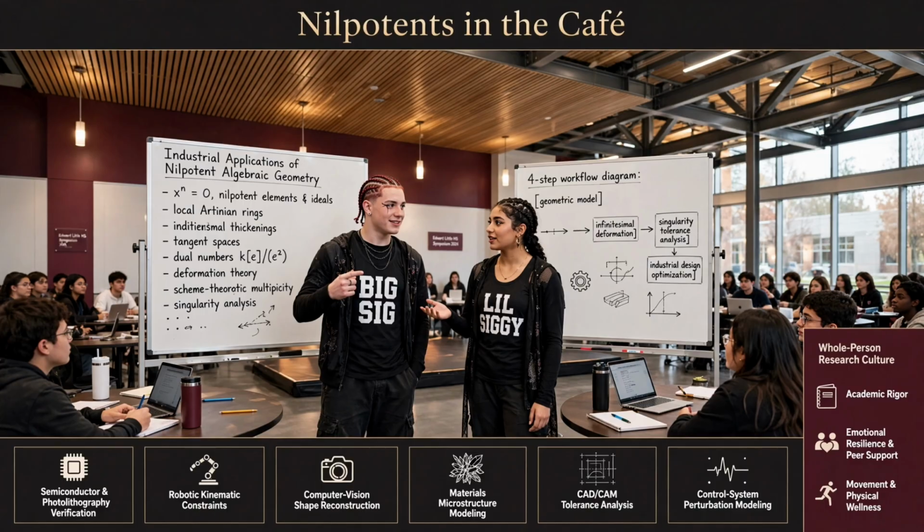Exactly. And this brings us right back to our algebraic geometry. We know we can't use the useless linear approximation, so what do we do? We construct a nilpotent approximation? Yes. We construct a nilpotent approximation of the control vector fields. We inject our self-destructing epsilon into the robot's navigation matrices. Wow. The complex nonlinear dynamics of the physical robot are replaced by a nilpotent Lie algebra of order k. Because the nilpotent element guarantees the algebra truncates cleanly, it yields a triangular polynomial system that the computer can actually integrate in closed form. We generate a perfect finite jet of the local movement possibilities, explicitly including all those Lie bracket wiggles.